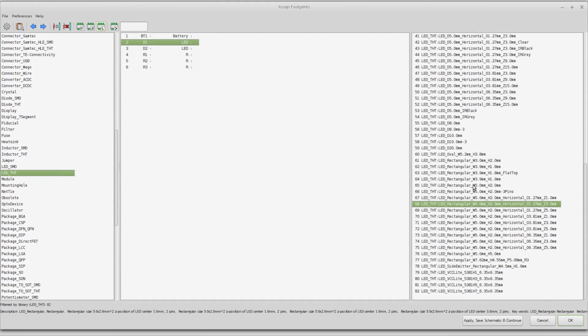So you start looking around, and ultimately what I want everybody to do, for the most part, except for some really super duper jelly bean stuff, and even that, I want us to make our own footprints. I want us to develop our own library. I feel like the more you get used to doing this, the easier, of course, it becomes, and the less willing you are to sacrifice any kind of board layout for something other than your own.